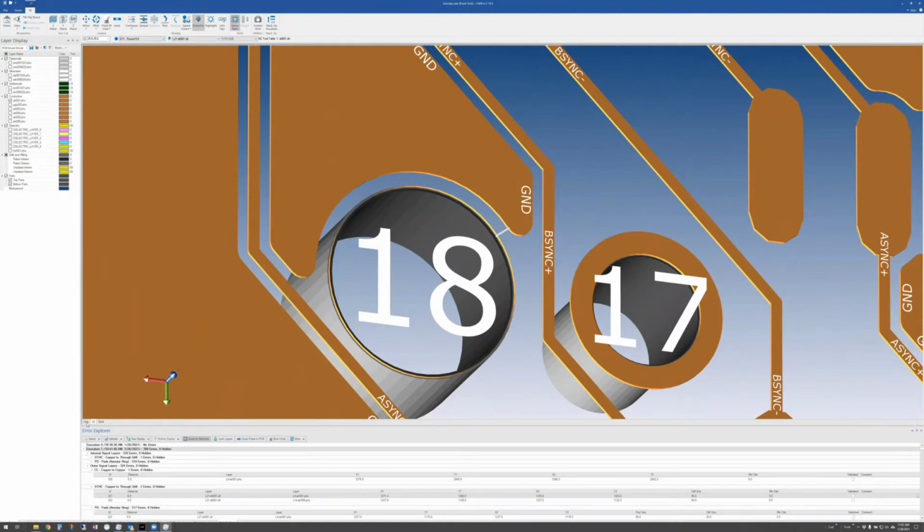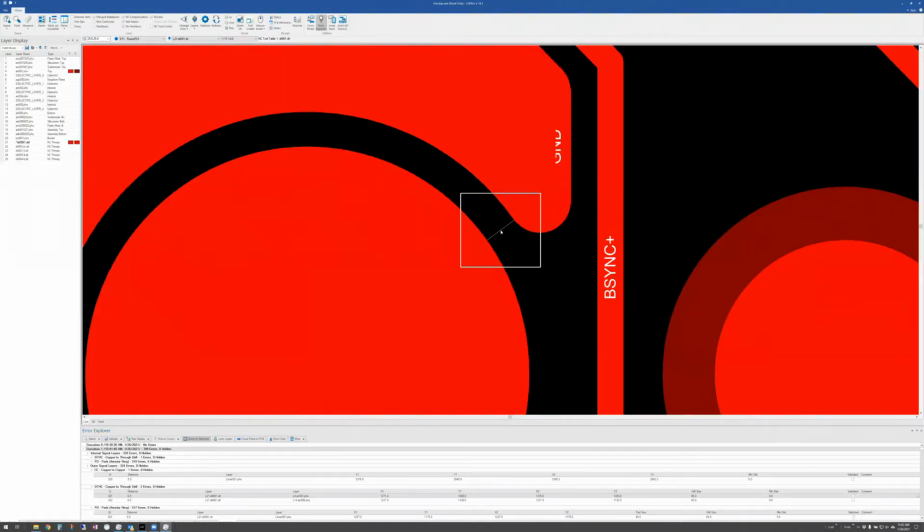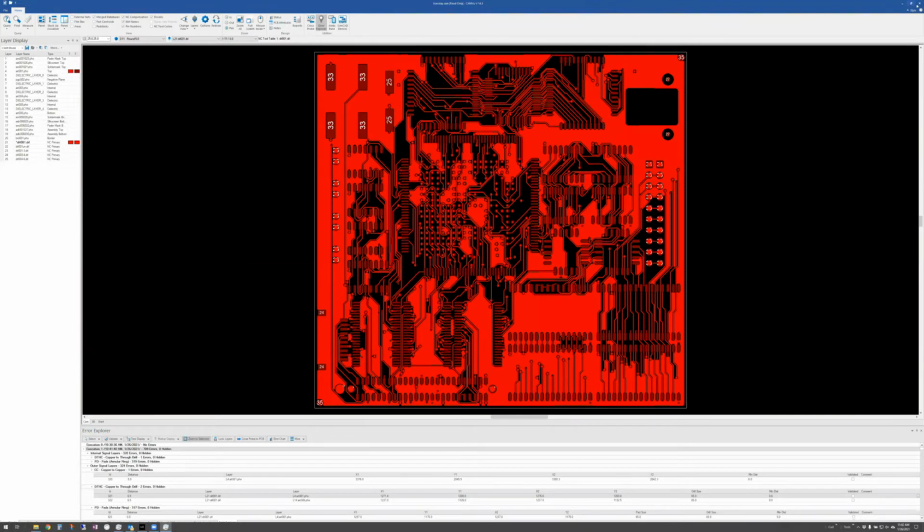Okay. All right. What I'm going to do now is get out of CAM350, and we're back into CAM350, and let's talk about some of your other questions here. And I'm going to skip the dimensioning to the last one, and you'll understand why when we get there. But how to add a layer and the different types we can add. Okay. So whether this layer display is docked or not, that little plus right there is where you can add a layer.